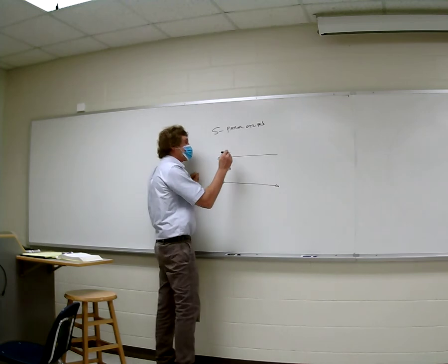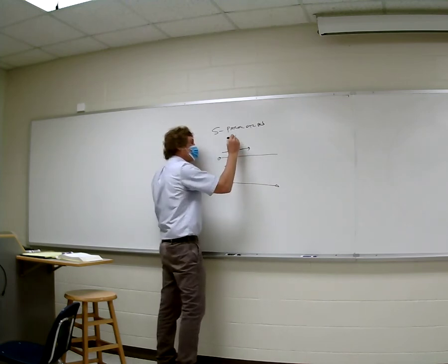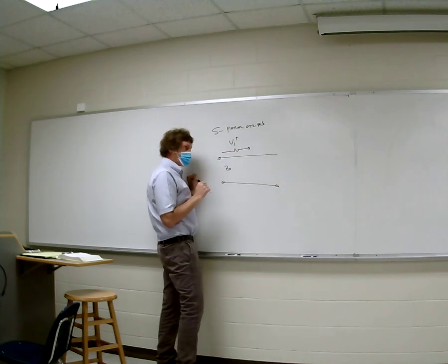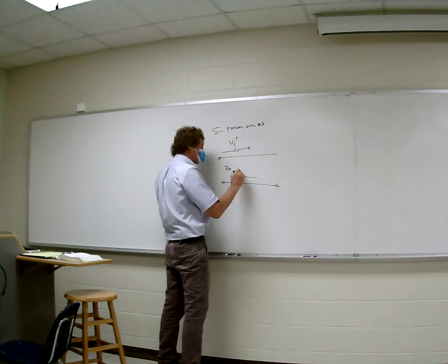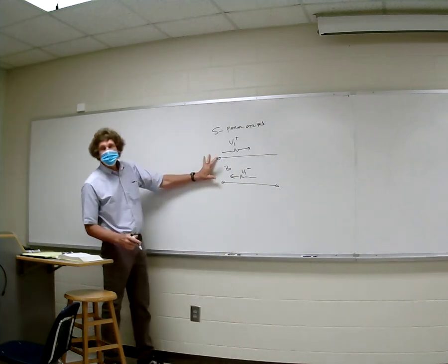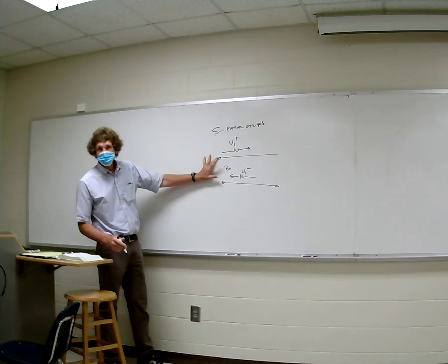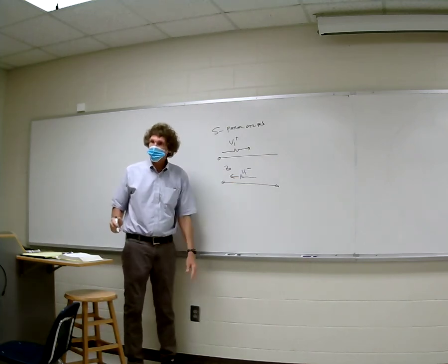And there's going to be information going. There's going to be some V1 plus information propagating that way, and there's going to be some reflected information, V1 minus. Now that V1 is developed across the transmission line from the plus to minus lead, but it is a wave traveling that way nevertheless. You all follow me?